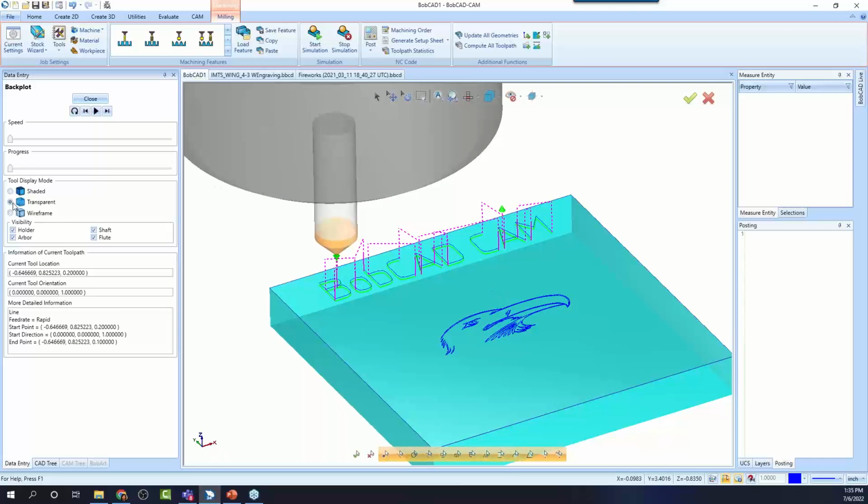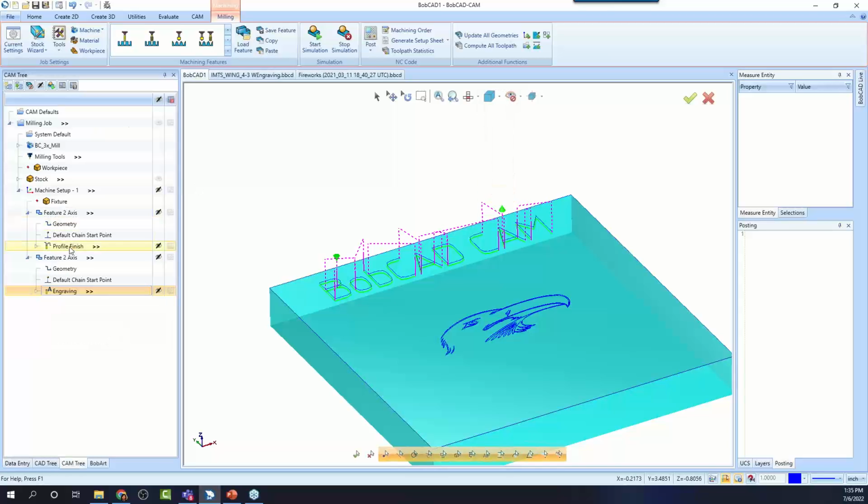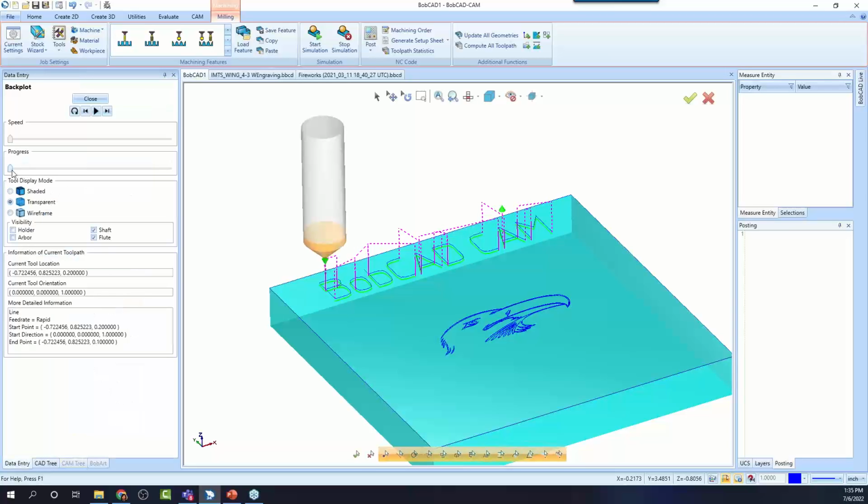for this, but again, trust me, I'm bringing the topic up on purpose because really, if you're engraving, you should be using the engraving feature, and that's where your consideration most has to do with intersecting geometry. Okay, and then your profile operation. You can utilize a profile operation, but it can run into some scenarios where it doesn't cut where you want.